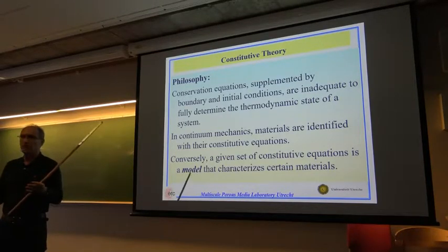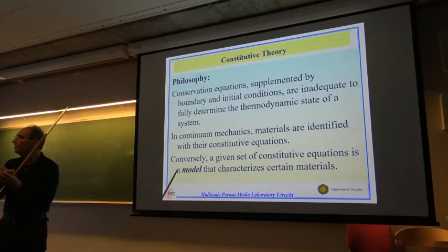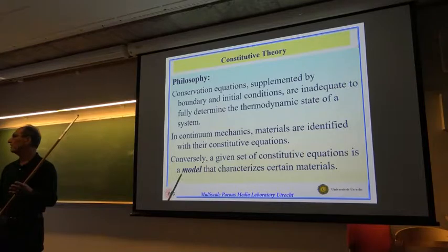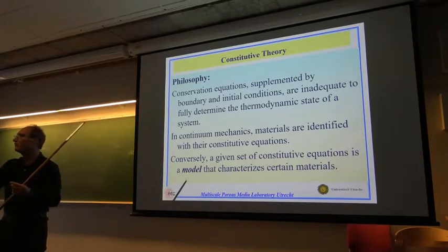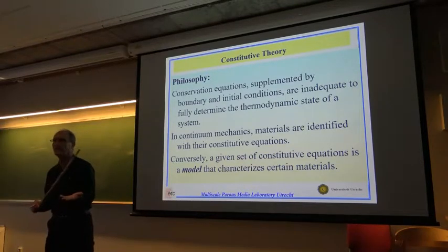You say, look, I have this material, I have studied it in the laboratory. If I impose a velocity gradient on it, it reacts and I experience forces, and I have shown that these forces are proportional to the velocity gradient. Perfect, then we write stress tensor is proportional to velocity gradient. Now, you have 6 equations there. That takes care of that.